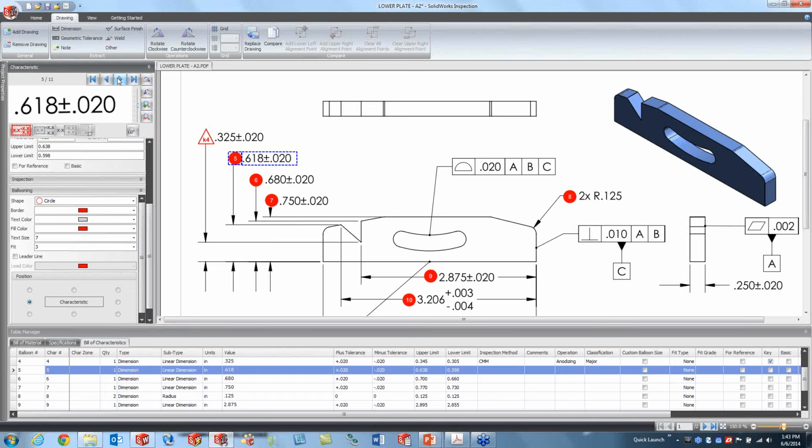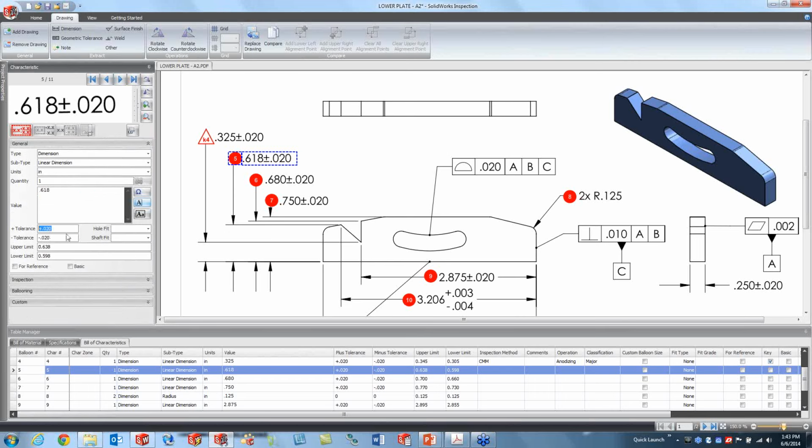What we're going to do is modify the tolerance on this, and I want you to see exactly what this thing does. I'm going to manually modify this tolerance. In this case, I'm just going to call this a 0.05. Because of that, it's going to recalculate that upper limit quite a bit. Now, in the event that we have a capture that maybe went awry because there was too much geometry grabbed with the window or something of that effect, we can actually recapture directly from the capture up at top here.